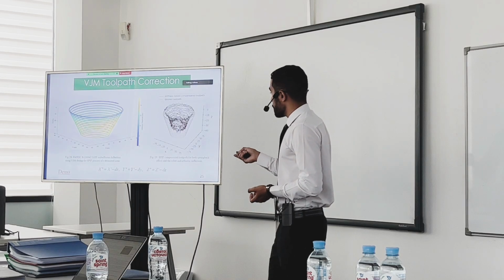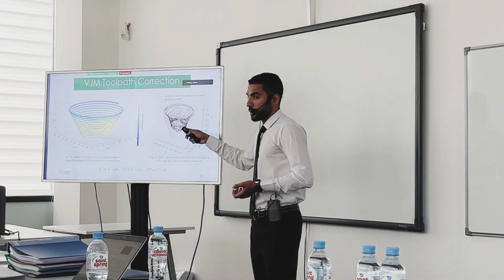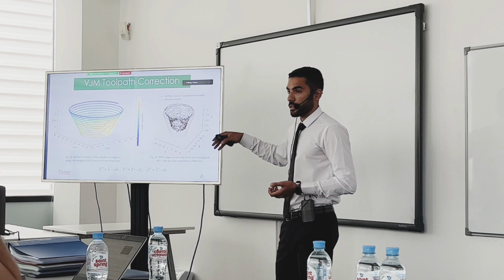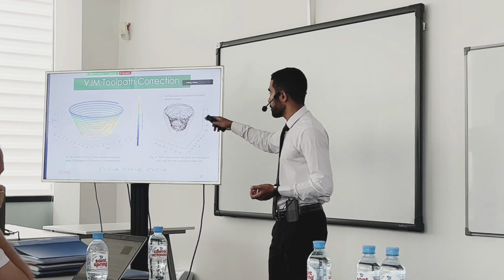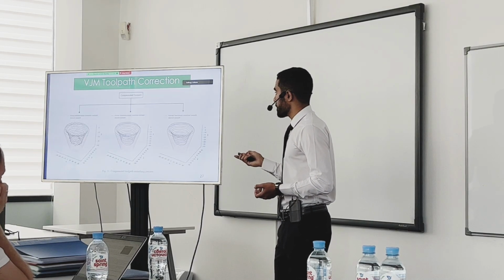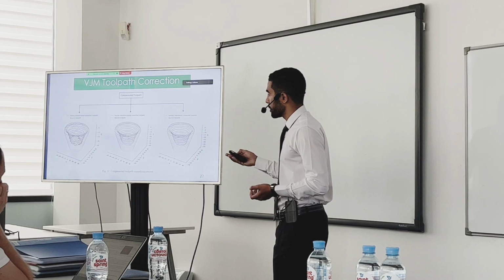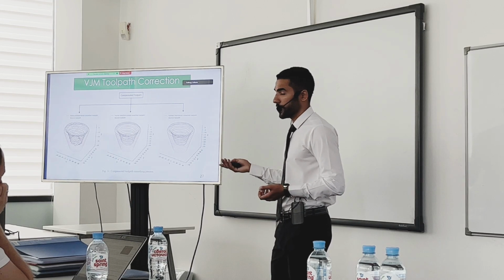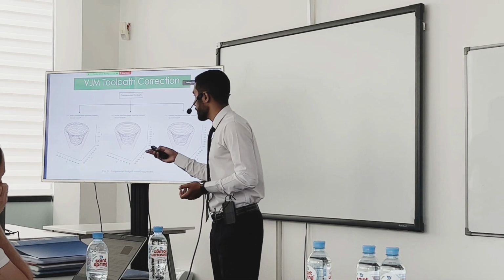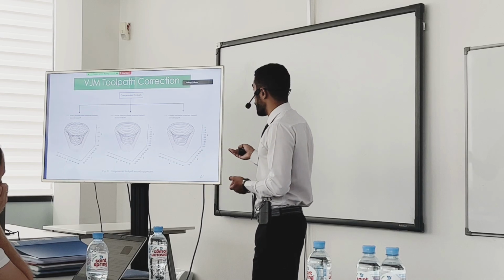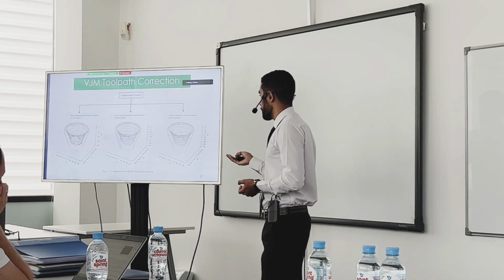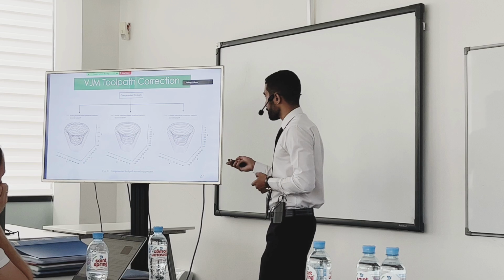As you can see here from the obtained tool path, there were some abrupt and sudden changes in the tool path. This has been dealt with by applying different smoothing techniques. For example, I used the sliding window, Fourier transform, and the Kalman filter, Kalman smoothing.